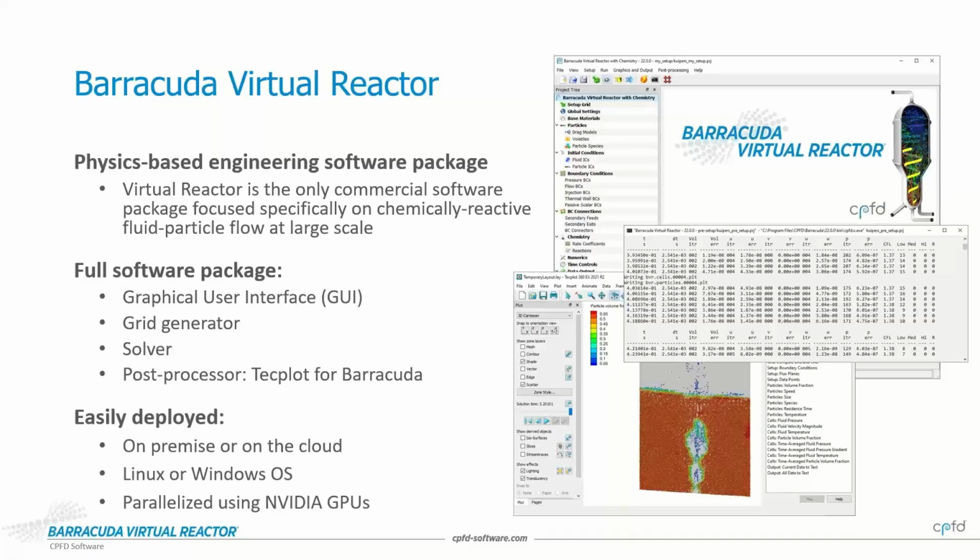There are software packages that model particle interactions at high resolution, such as DEM tools, and there are CFD codes that can capture dilute particulate flow by abstracting it against fluid dynamics calculations. But in many systems, simulating both phases with high fidelity is critical. And as such, Barracuda models continuous Eulerian fluid and discrete Lagrangian particles, coupling them tightly and resolving them simultaneously. I'll get more into the unique features of the software shortly.